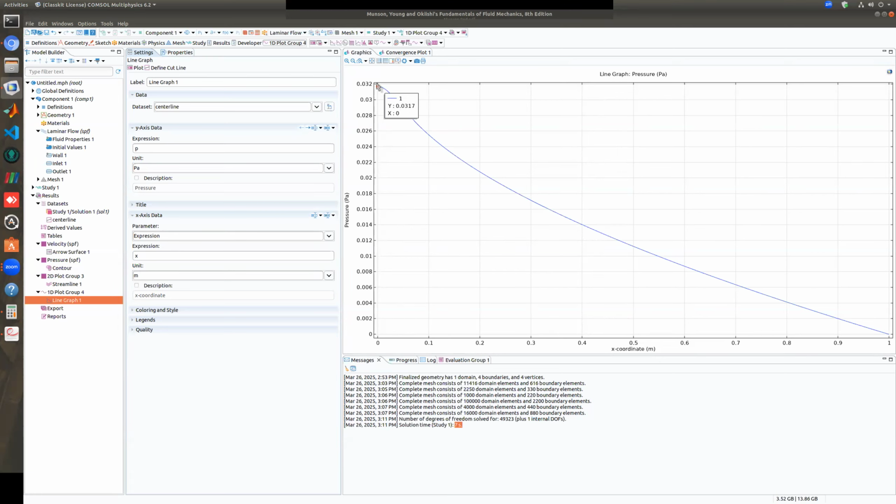Initially in the entrance part, there is a nonlinear pressure drop. And then after a certain point, maybe roughly here, it becomes almost constant, right? So this is the fully developed part, roughly, and this is the flow development part. In the flow development part, we have an excessive pressure drop. If you extend this linear part all the way to the entrance, there is a little bit of extra pressure drop here, and that is due to the entrance effects, the accelerations, decelerations, the flow development effects, right?